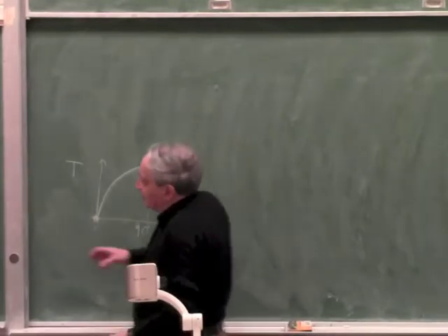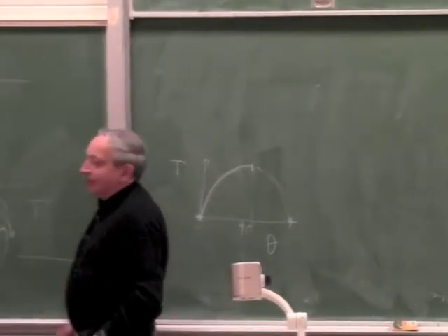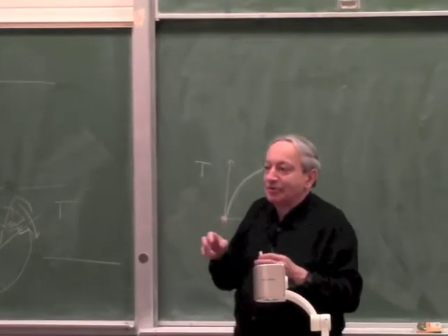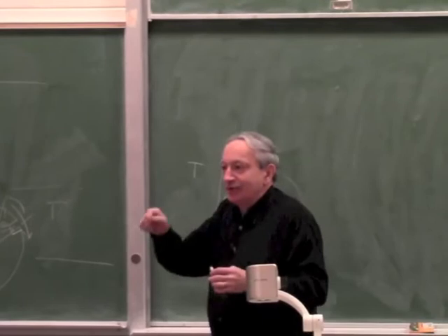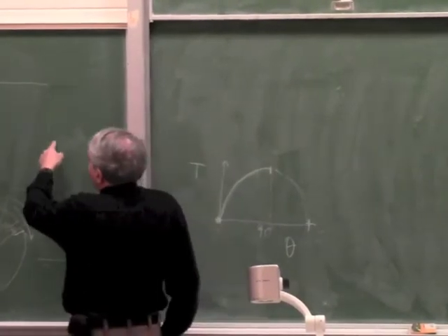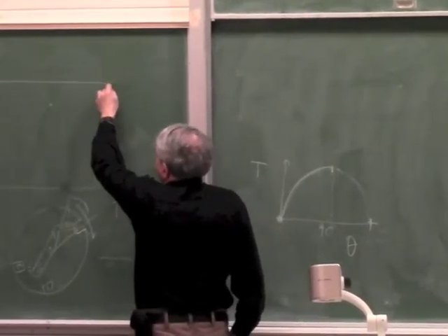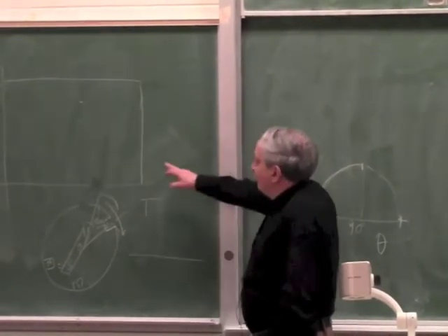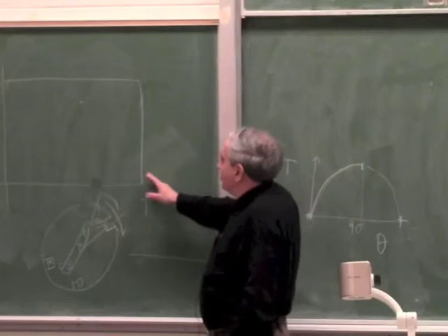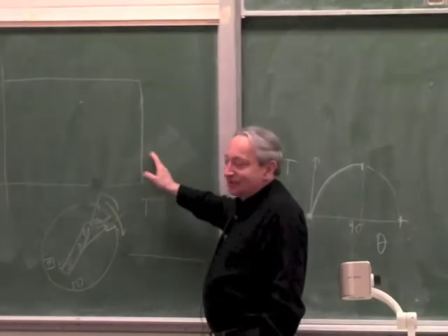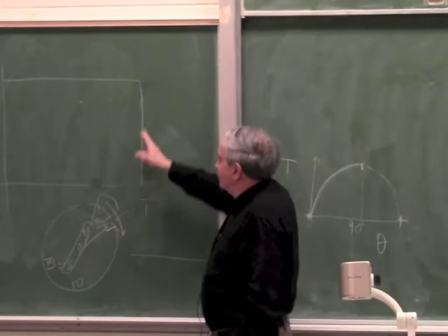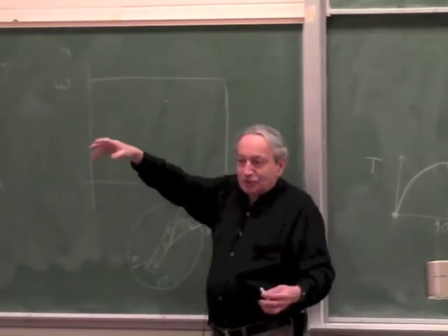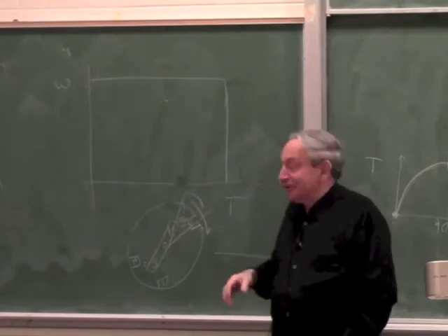And as you increase the torque, it starts winding up until it breaks lock. And when it breaks lock, it starts vibrating. It loses torque, just like a stepper motor when you stall it or when you try to run it too fast. So what really happens, it doesn't go down. The line doesn't really look like this, because if there was really a solid line here, it would imply that you can use a motor as a constant torque motor. See, this line implies that torque is constant and you can change the omega. Okay, and there are such motors which are used as constant torque, but that's not really what happens.